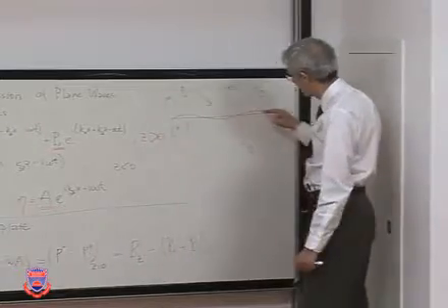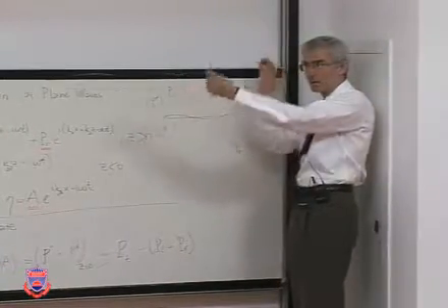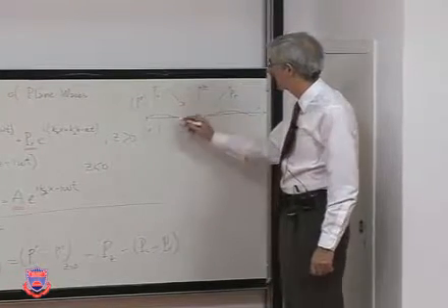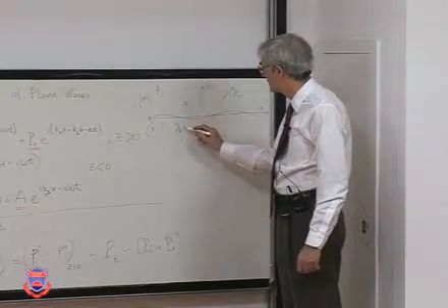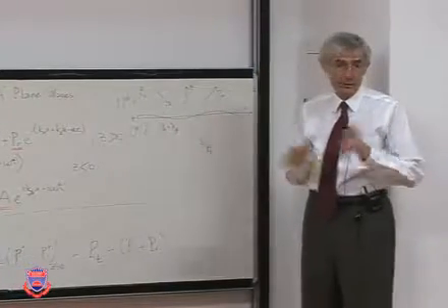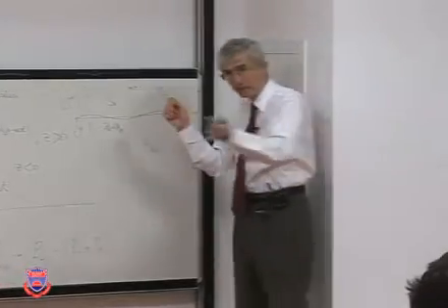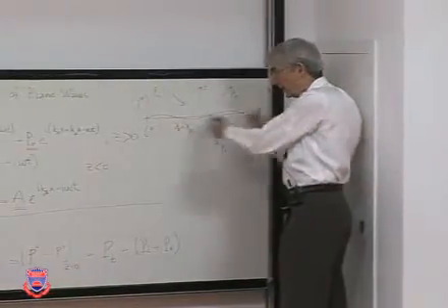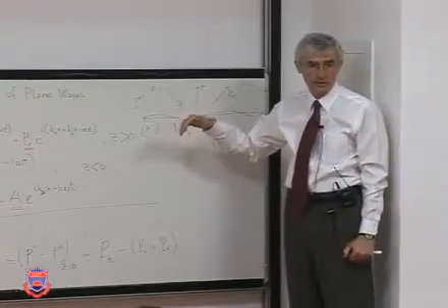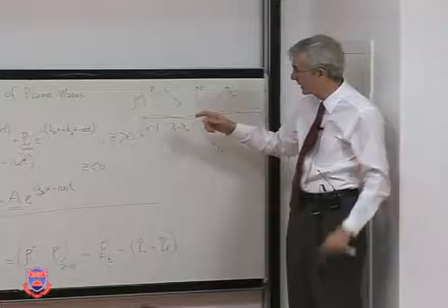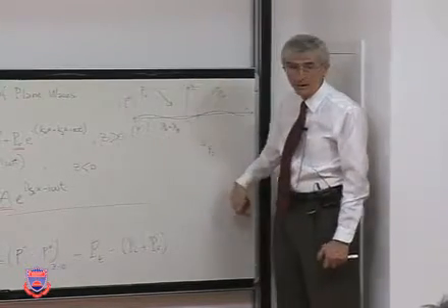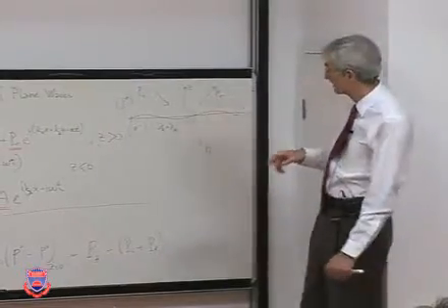And what the plate sees when that pressure comes is its footprint in the x direction, meaning lambda x, which becomes the bending wavelength of the plate. That's all the plate sees. This wave is now a bending wave that's traveling on it as a result of the incident wave. The plate doesn't know anything else. Because of that, it radiates out to the other side, which is the transmitted sound.